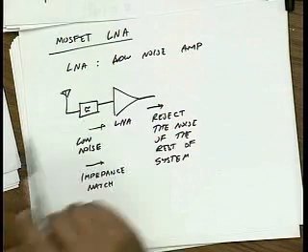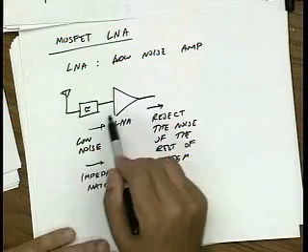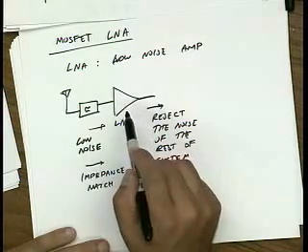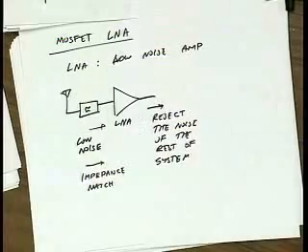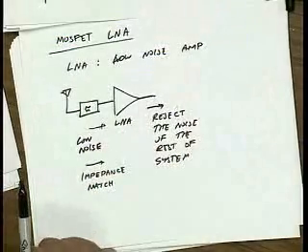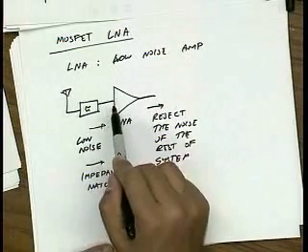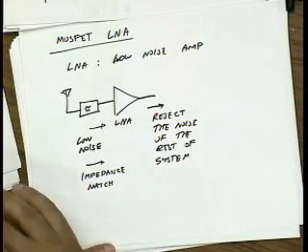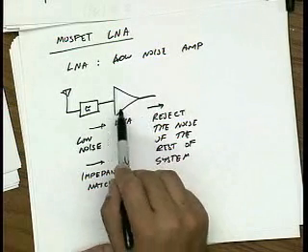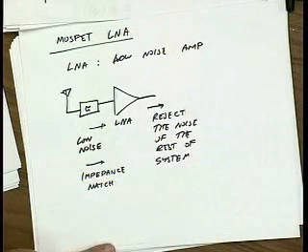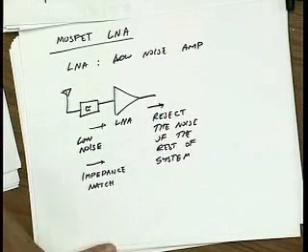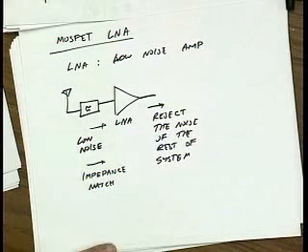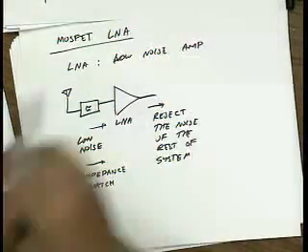It's related to EE117. The reason is that usually there's a transmission line from the antenna all the way to the input of the LNA. That might be a physical cable, or it might be just a short section on a PC board. And that transmission line will take the input impedance of that LNA and transform it to some value. Now, if you have an impedance match, in other words, the input impedance of the LNA is equal to the characteristic impedance of that transmission line, then at all frequencies, the antenna sees constant impedance. So that guarantees that I'm always going to transfer a given amount of power from the antenna to my LNA.